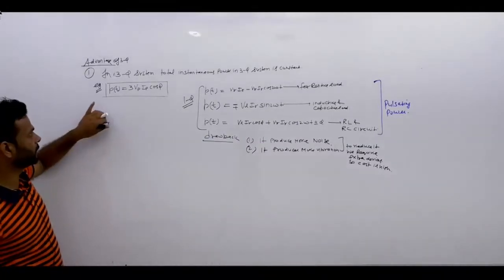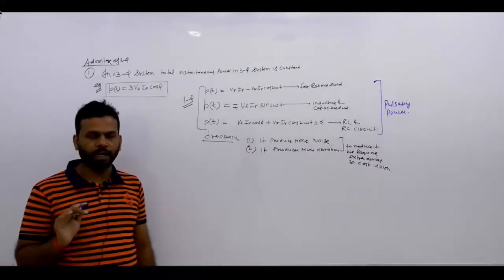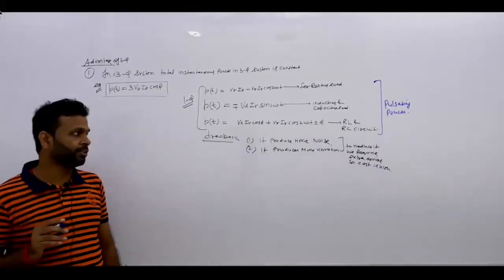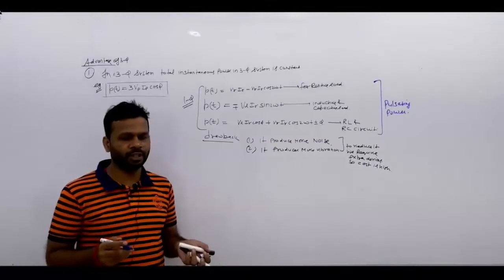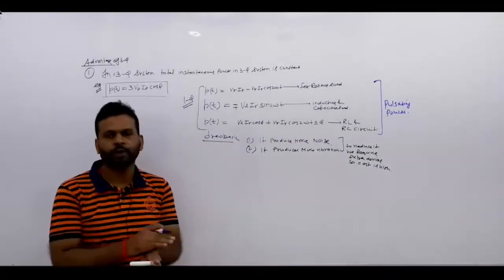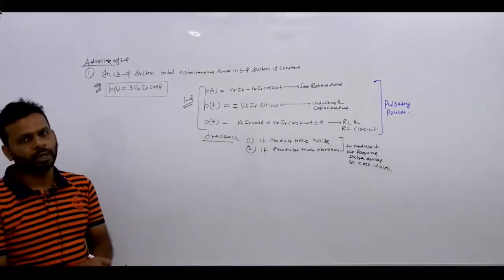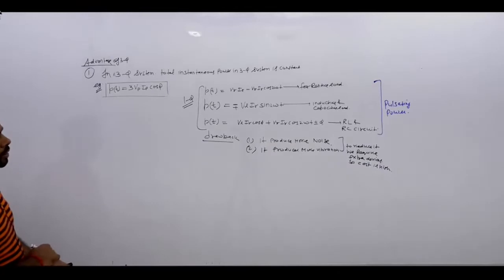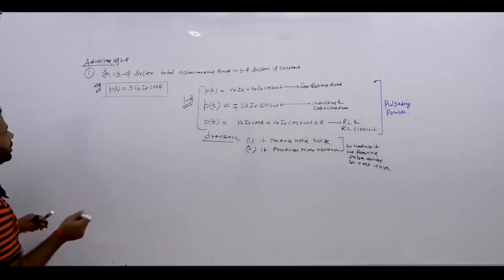In that we have studied that three-phase instantaneous power is constant, while the single-phase instantaneous power is pulsating, and due to the pulsating nature of power, it is having more noise, vibration. So to reduce it, we require extra or auxiliary devices. So the cost of the system is high. So this is the reason number one. That's why we are using three-phase power. Okay. Now second advantage. Let's see what is that.